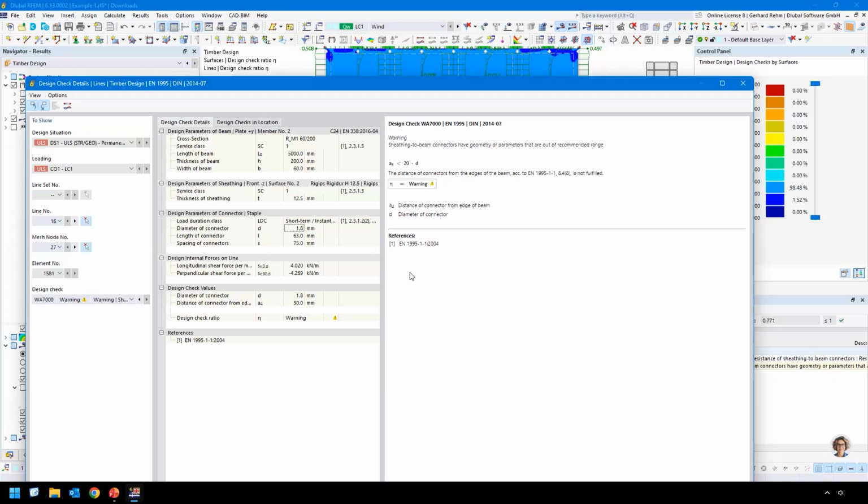We could use smaller edge distances by using the leg of the staple as a nail. Of course, in this case, we need to know the width of the back of the staple, and we would need the angle of the staple to the stud. This information for now we don't have and we don't consider.